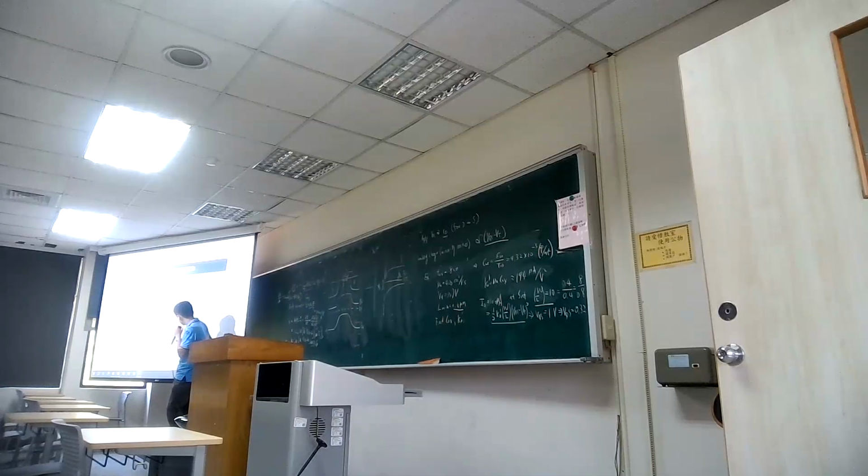Okay, so that will be interesting to see. You can see the depletion region is increased, and we have the Fermi level separate from each other. We have an EFN and an EFP. And the EFN will go down because we say it is the majority carrier. Okay, so for majority carriers it goes down, and we split the majority carrier away. And then it will continue to the original part of the N-type semiconductor. For the N-type semiconductor, we still have the Fermi level on top of the intrinsic level. So that is what we have.